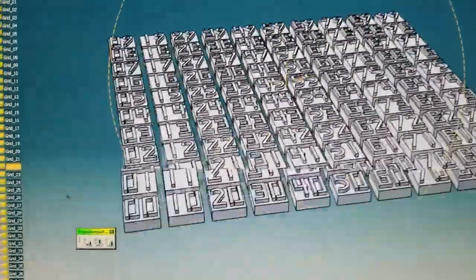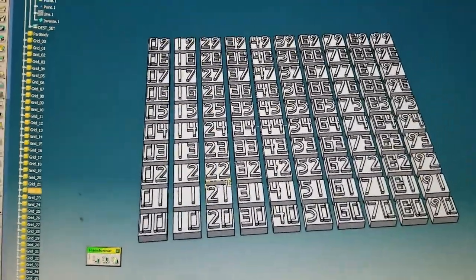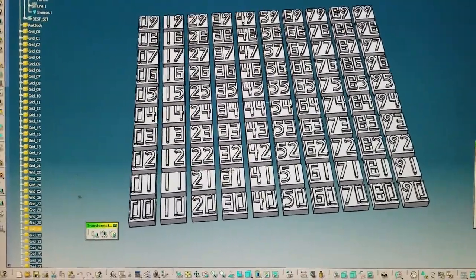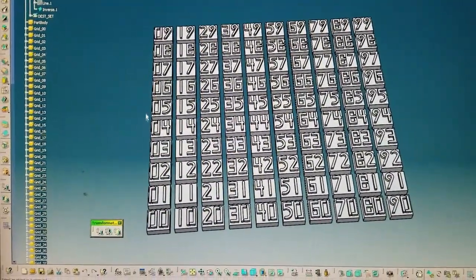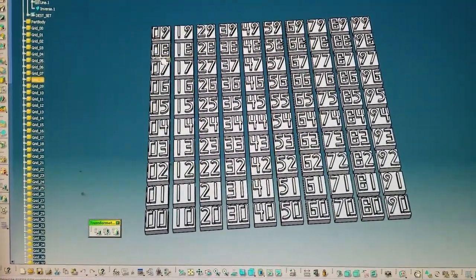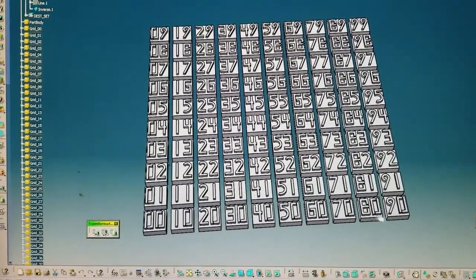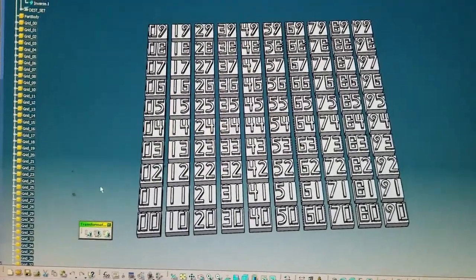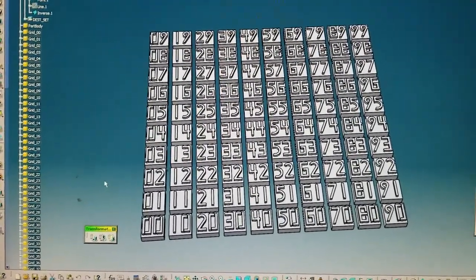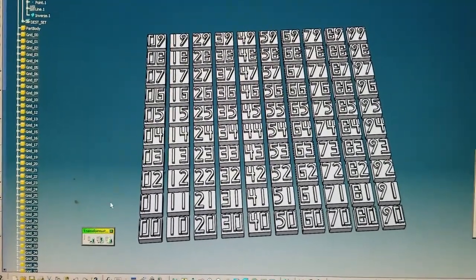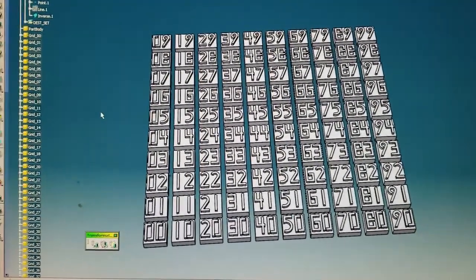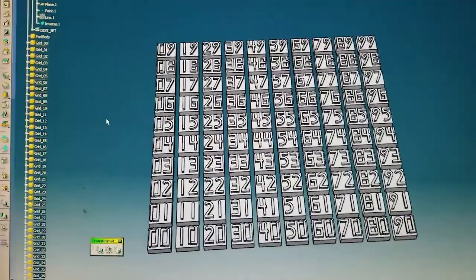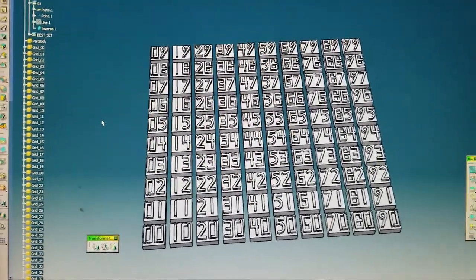I'm going to use this to calibrate some 3D prints I'm doing with the Sintratec SLS printer, and the bed is 11 by 11, so this is 10 by 10 little one centimeter boxes with numbers. With the numbers I'll be able to tell which areas are not sintering correctly, because I'm getting some sintering issues around the perimeter. I assume the corners are going to be bad, because that's pretty typical. The corners are kind of a no-go zone until you really get your machine fine-tuned.